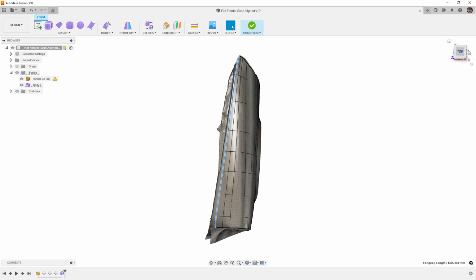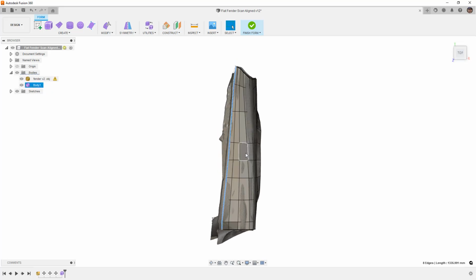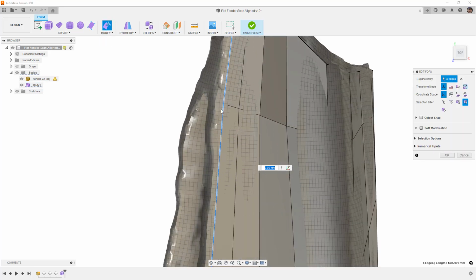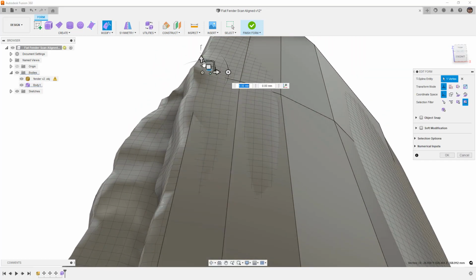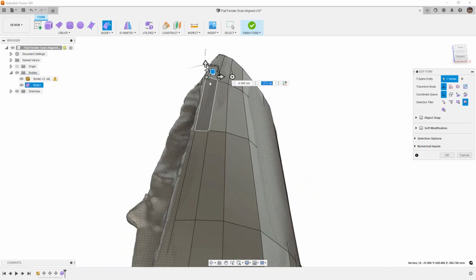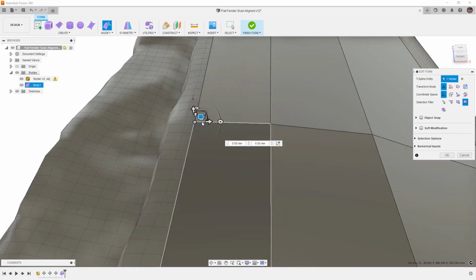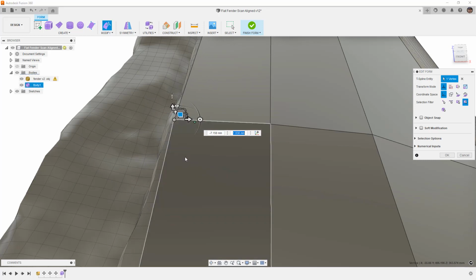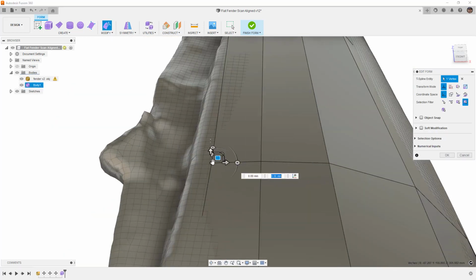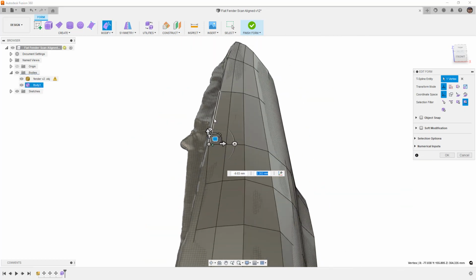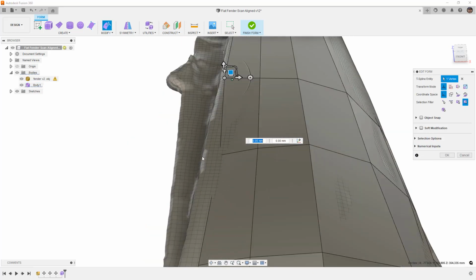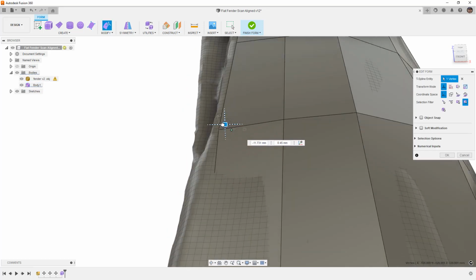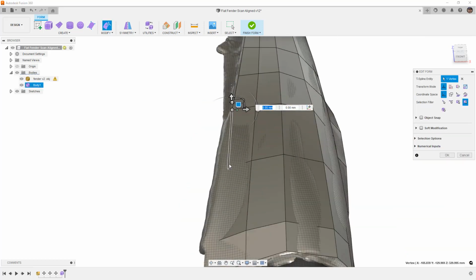But I want to take this edge and push it a little bit closer. Once again, something that's important for us to do using the box display. So I'm going to take these vertices and pull them out. You'll notice that it ends up going a little bit below, and that's okay. It doesn't have to be perfectly above, but moving in plane can kind of help us. Ultimately, once we're happy with the overall shape, we can extrude this edge with a crease and go down to make that lip. We're not quite there yet, but I want to just get a little bit closer to that edge. Again, it doesn't have to be perfect.